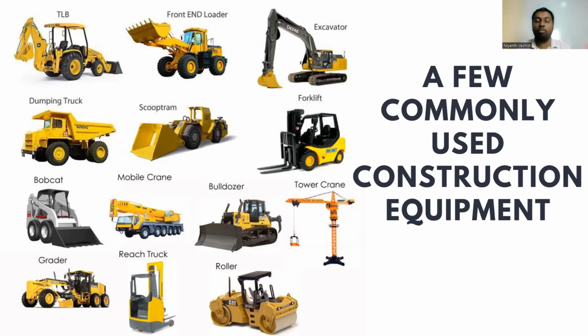The next one is the scoop tram. Scoop tram is normally used in roadway projects wherever you need to excavate a small thickness but for a very huge length. So excavator is used when you need depth. Scoop tram is used when the depth is less but the length is more.